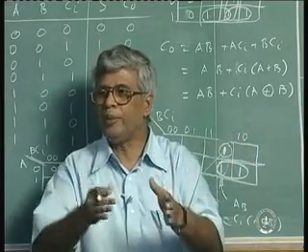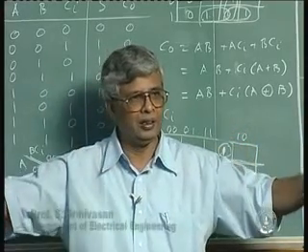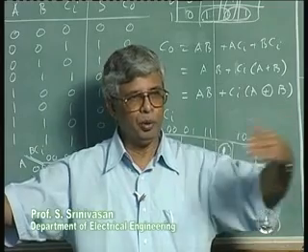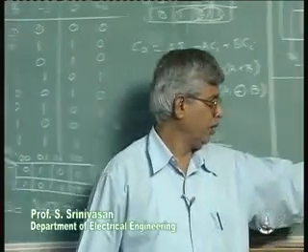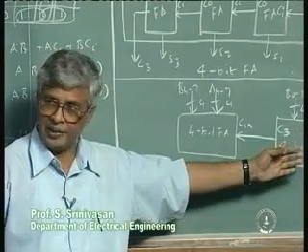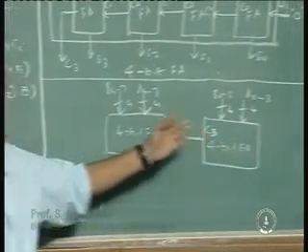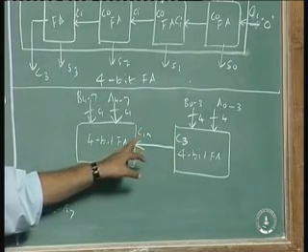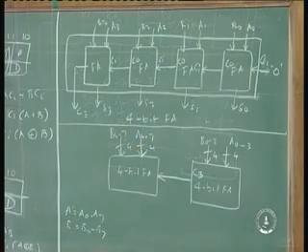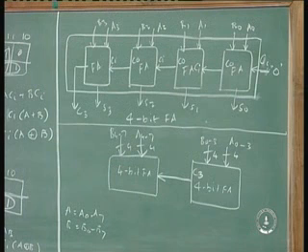If it is an intermediate stage in a multi-bit addition, then my input carry would be the output of the previous block. This block of 4 bits, output feeding into a block of another 4 bits. The output carry C3 goes as input carry Cin, and output of this is C7.